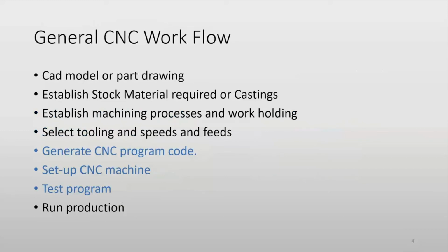This one should be straightforward for you because you already know. First, I need to have a CAD model. What we've done, we imported a CAD model in CAM. The same thing if you deal with a CNC machine: you upload a CAD model, you put the drawing in it. And then you have to define the material. We did it quite early in the stage of the CAM. Do you remember in the workpiece, we went and defined the material?